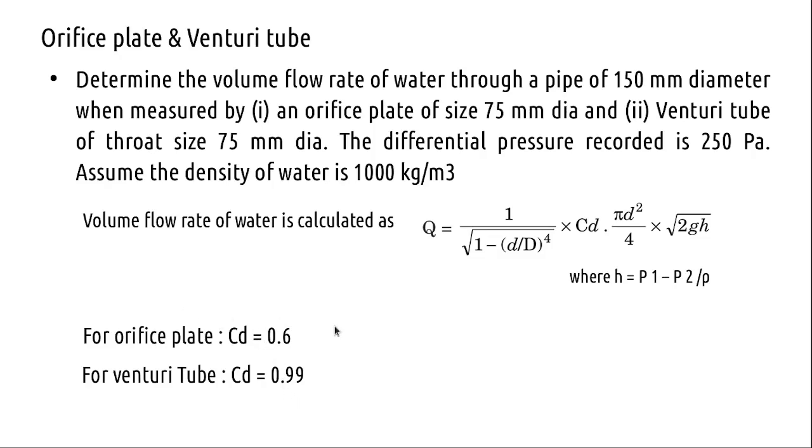0.99. One reason is that the orifice plate is going to reduce the pressure head downstream. It's sort of blocking the flow. The pressure downstream will be reduced as much as 40%. For the Venturi tube, the pressure downstream, that is after the throat, the narrow part or vena contracta, the reduction in pressure is around 10%. Due to the same reason, Venturi tubes, even though they are complicated, are used in situations where you cannot tolerate reduction in pressures.